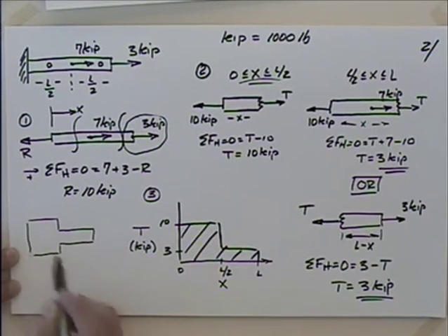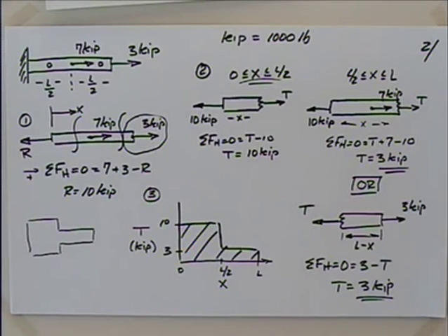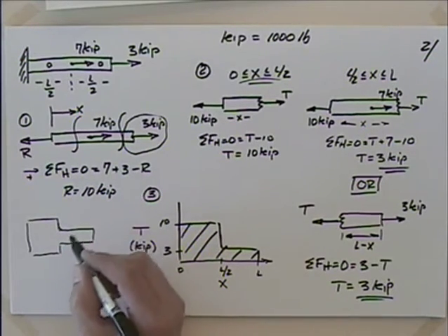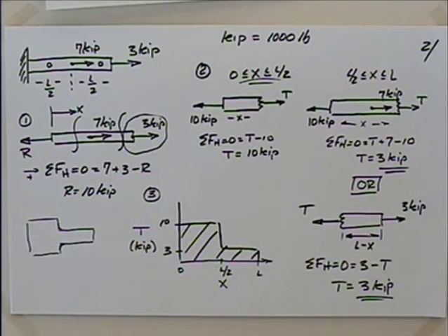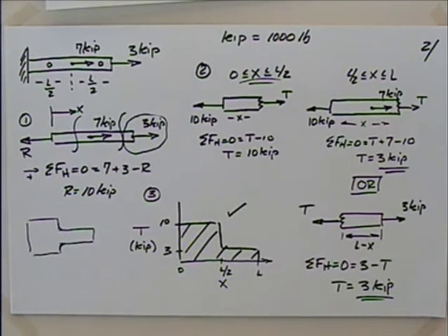And this is where you as an engineer have to start to think, well, is it worth that? If we're going to put it on the side of some ocean-going barge, it's probably not worth reducing the cross-section. If we're going to put it where it costs several $1,000s to put a pound into space, then it's probably worth going through that machining process and whatnot. But that brings problems of its own. We'd have to probably put some sort of radius in there, or we're going to have a tremendous stress concentration and whatnot. So these are all things that we will have to deal with, but unless we have something like this, we're kind of shooting in the dark. Questions with that?